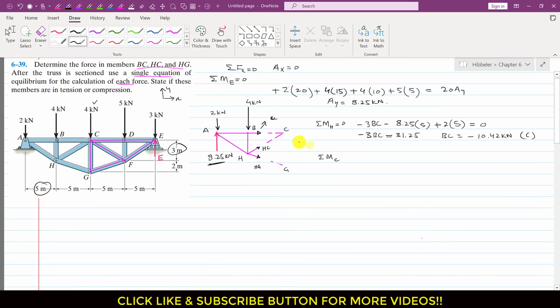So if I apply the summation of moment about point C, this BC and this Hc will not come into our equation, and we will have only this one unknown in our equation, right? So if we apply the summation of moment about point C equals to 0, as we can see, this Hc is making some angle with the horizontal, right? It is making some angle.